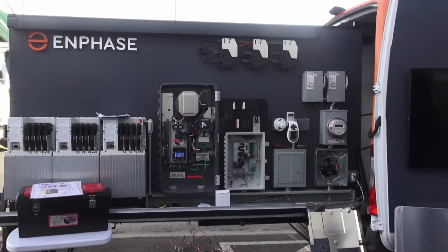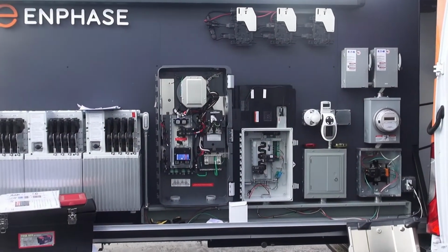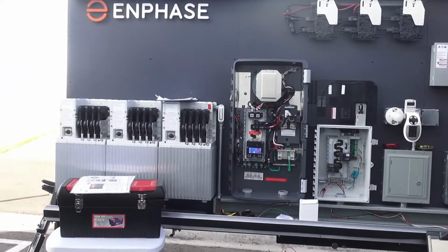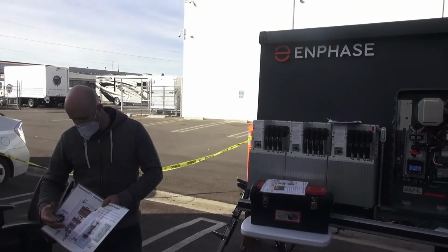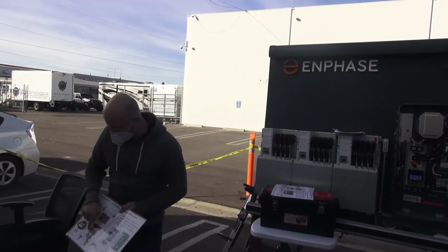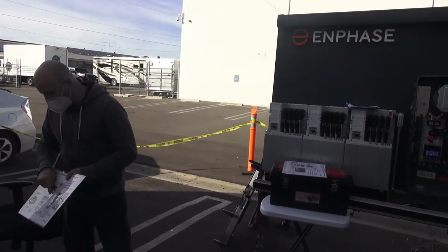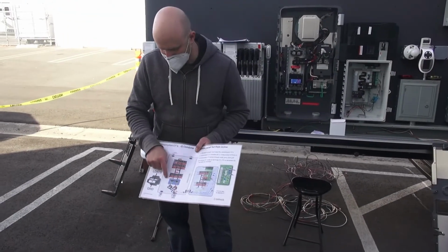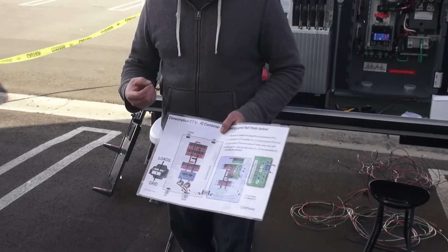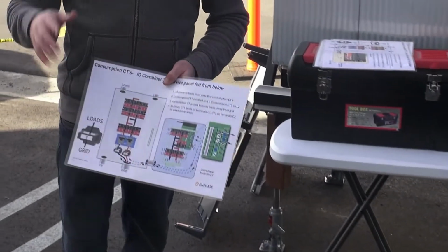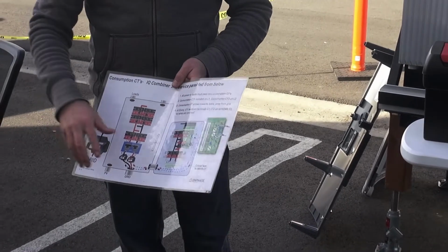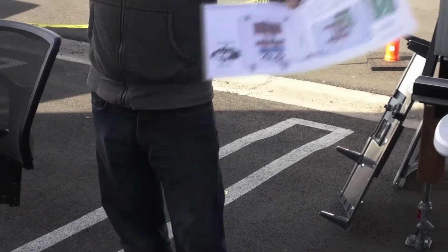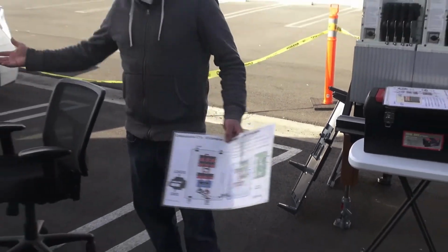So you try to locate it. We try to locate those consumption CTs somewhere where we're going to measure everything. See this kind of image here? If I put the CTs up here, I have a problem. Some of these loads won't get measured. Different location. Now, I'll tell you, sometimes if you've got some interesting scenario and you've got one circuit here and that goes to the pool, sometimes you go, I don't know if I'm going to get it, right?